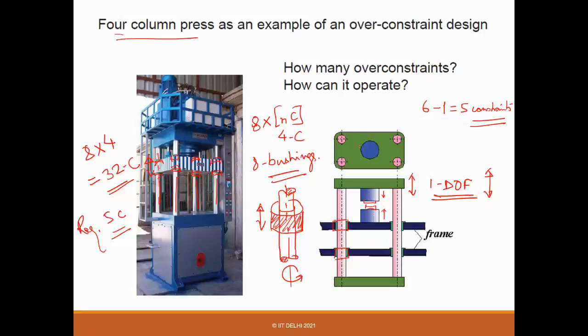Secondly, the straightness. What is the straightness of these guides? Locally, if they are not straight and there is a variation, there is a change in distance between the different points. That's the one thing. Now come to the slider part, which is moving up. They have holes. How perfectly can you make those holes precisely at those points? Again, the cylindricity, circularity, the distance between them.